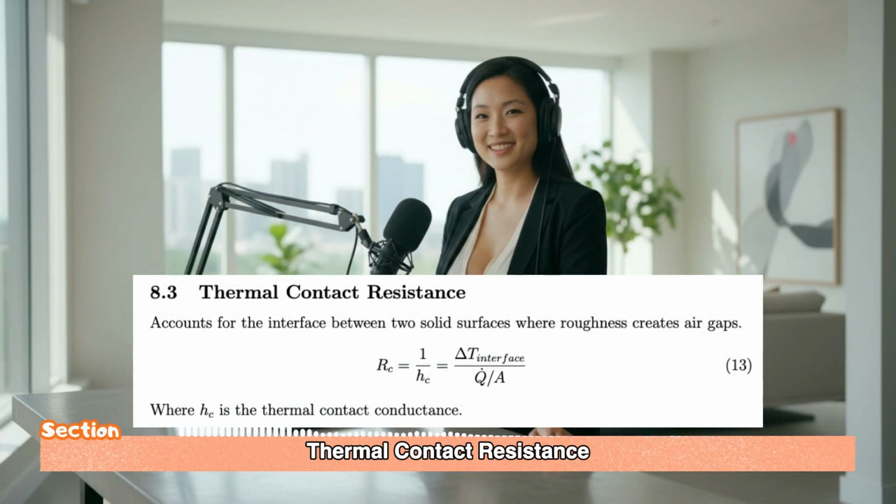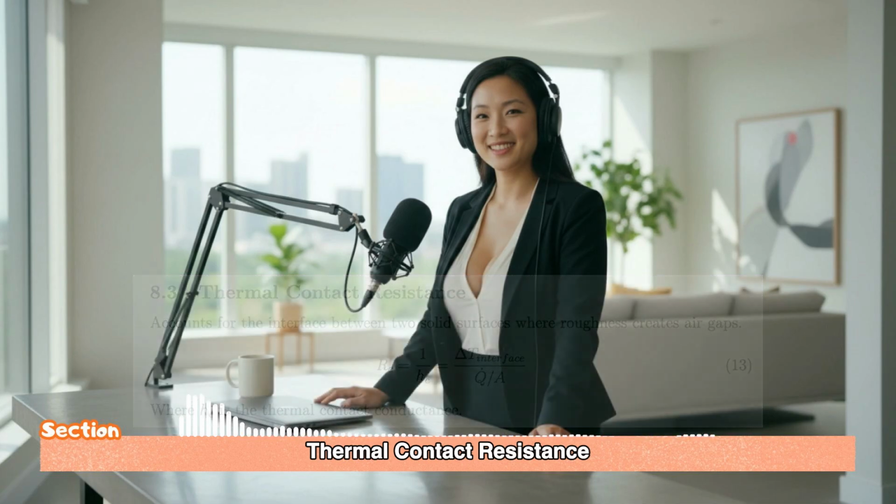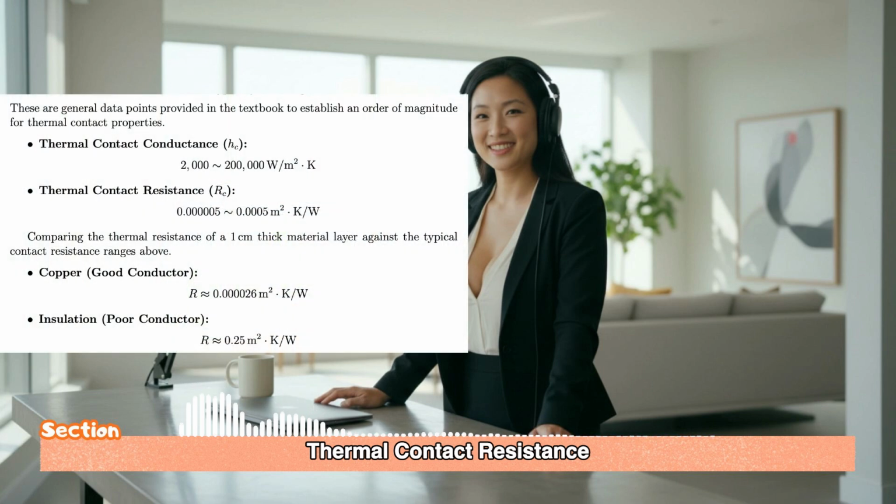RC equals 1 over HC. But because it depends on all those variables you mentioned, roughness, pressure, cleanliness, it's measured experimentally. The data is all over the place, but we have established ranges. And our sources say that typical values for RC fall between about 0.000005 and 0.00005 square meter Kelvin per watt.